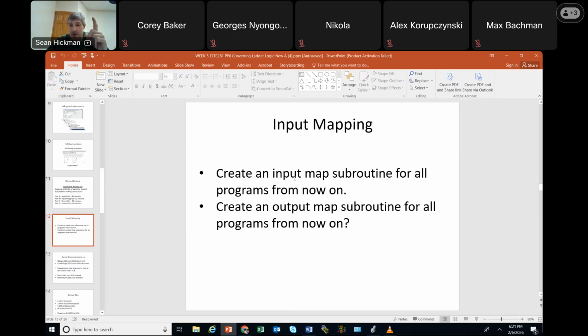All right, I'm going to tell you this. You only have one push button on the input, but you might be using that contact multiple times. On your output, you only have one light, but you only are going to have that programmed as once. So whether that output gets written, and then the scans don't hit right or not, it might not be as critical. Whereas if the input, as we showed you, if the scans hit at a different time and you've used the input symbol more than once, you can get a condition where the input is reading as true on one rung and false on the other. So the input mapping might be more important than having an output map sub.